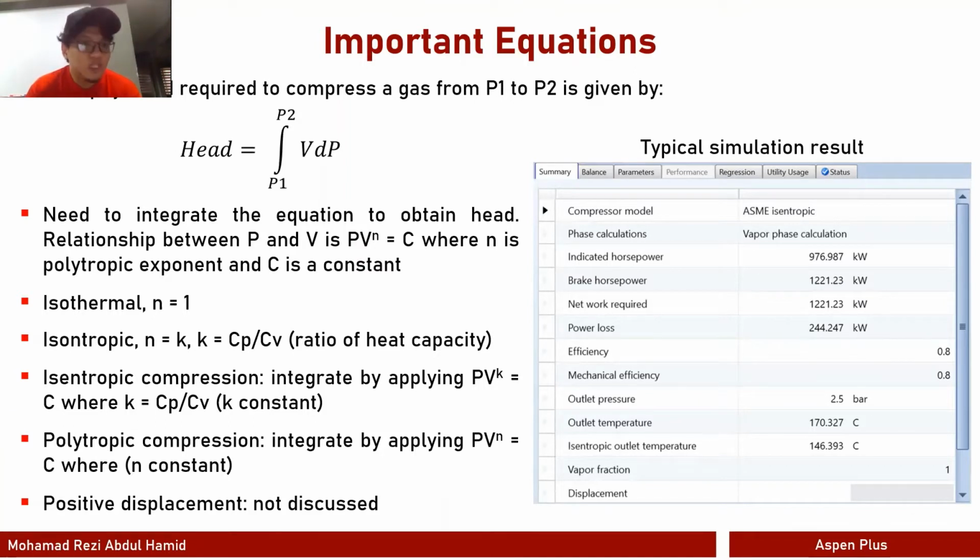Well, even though modeling or simulating compression process in Aspen Plus is pretty straightforward, what I observe from my students, especially in the integrated design courses or maybe in plant design courses, is that the students fail to see whether the result that they obtain makes some kind of physical sense or not. So especially when it comes to temperature increase.